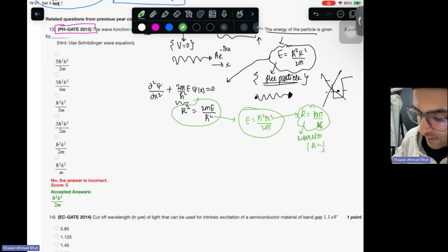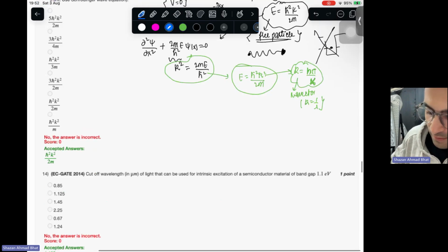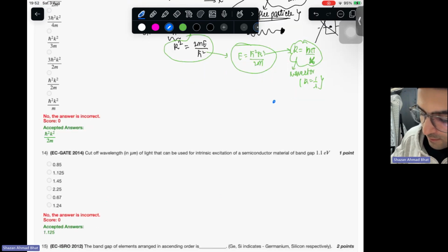So basically, there are two things I'll tell you. When you have a time domain and a frequency domain, you convert using the Fourier transform. If you have a spatial domain, you convert it into a wave number by something called the spatial Fourier transform. This is basically equivalent to 2 pi over x, a similar thing to f being equivalent to 1 over t.